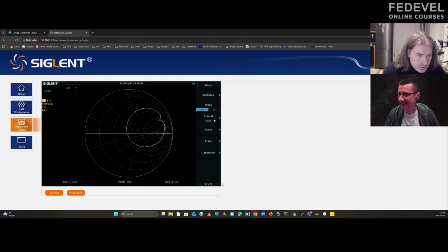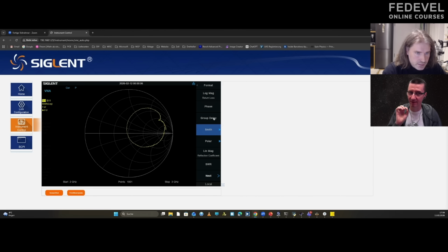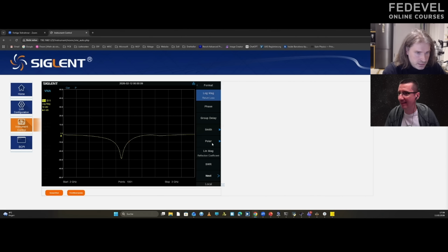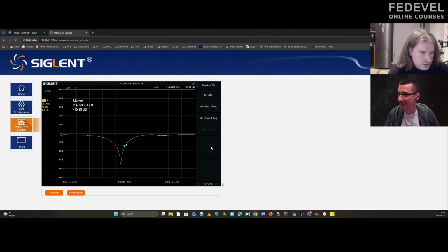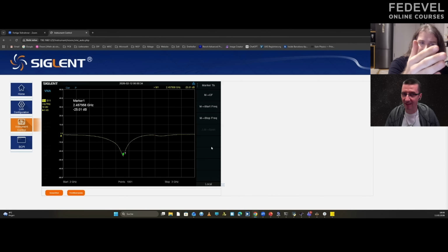Frequency. Let me look here. So now it is showing all the frequencies from 2 to 3. It's all the frequencies. Maybe if we look here on that one, it's better. Go here with the marker. So maybe a bit too low. If I cut it a bit here, it would go higher, but it's very good here. So we are under 10 dB, so it's a very good antenna. And you can also see in the picture, if I go with the hand here, that it is sensitive here. So the antenna is radiating here.